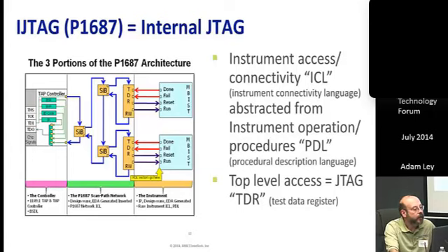And in effect then, that gives us a set of virtual test points that get placed onto the printed circuit substrate wherever that IC is placed. We'll talk a little bit then in the embedded instrument context about internal JTAG. Internal JTAG is a new standard for embedded instrumentation based on JTAG that is just closing its balloting process.